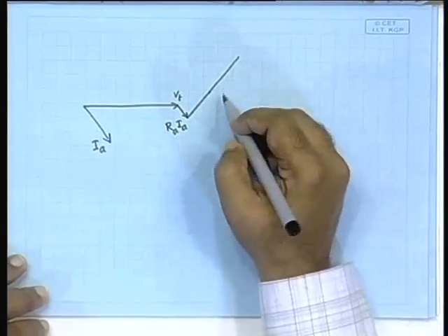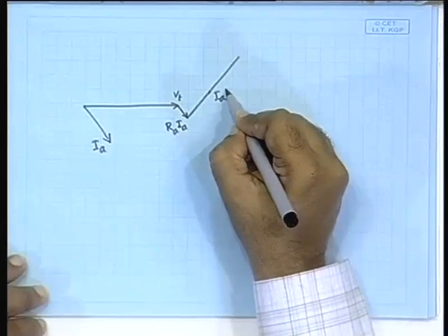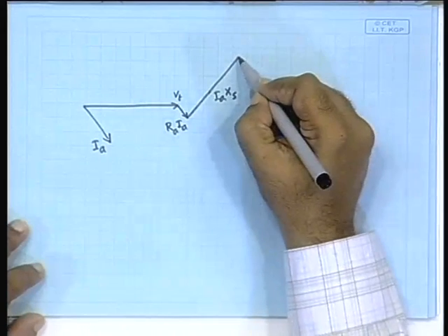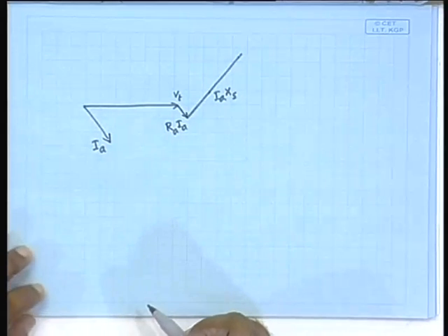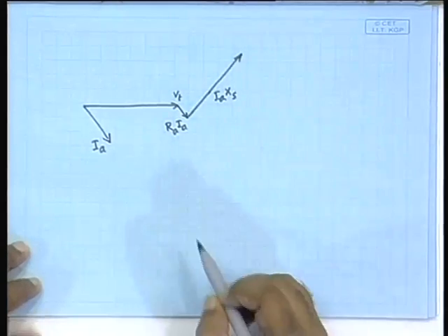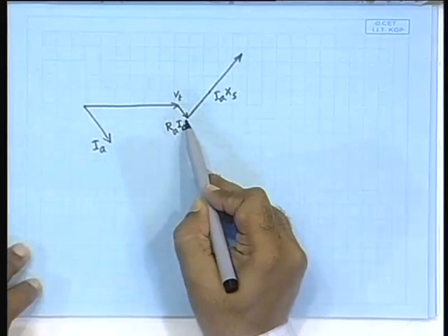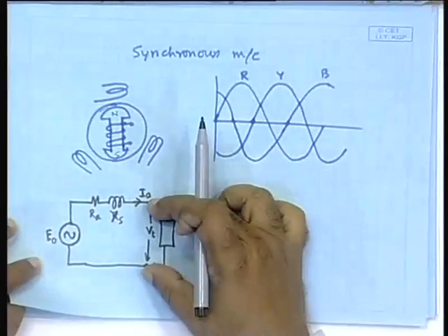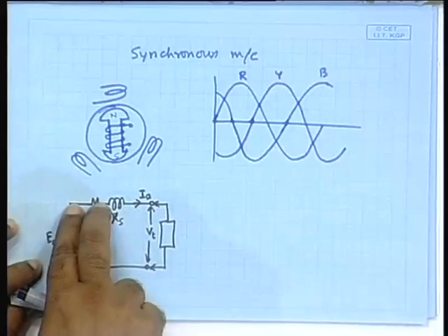Remember, this amount I_a X_s will be far larger than I_a R_a, because resistance is generally very small. So, you can see that this will be the drop. So, this voltage plus this voltage plus this voltage added together will give me the...